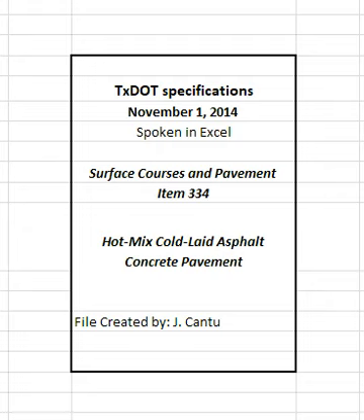Maintain at least a 2-day aggregate supply through the course of the project unless otherwise directed. Stockpile aggregate for each source and type separately. The engineer may reject stockpiled materials that come in contact with the earth or other objectionable material.